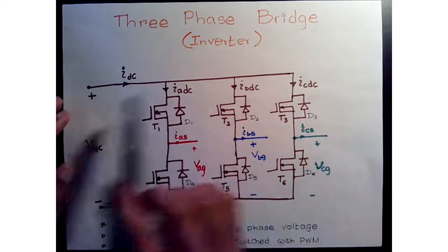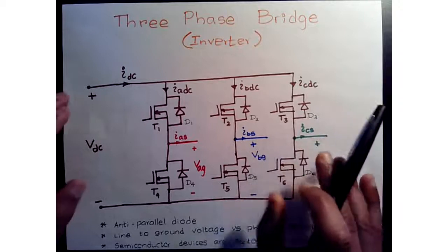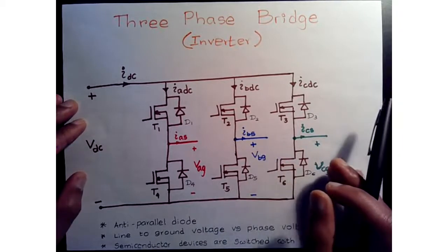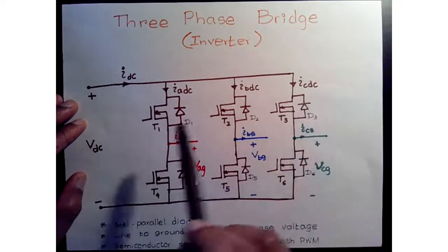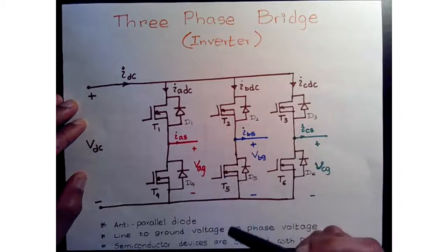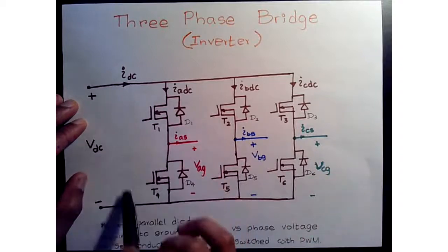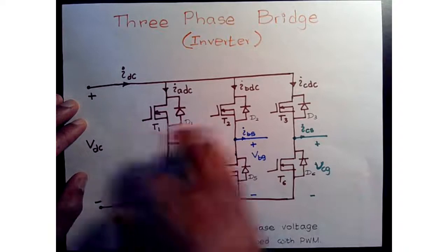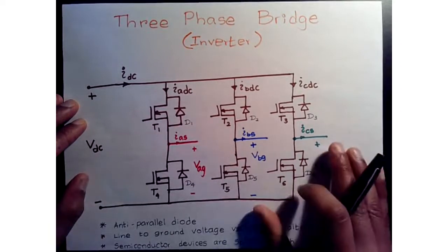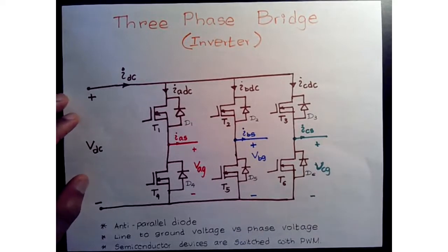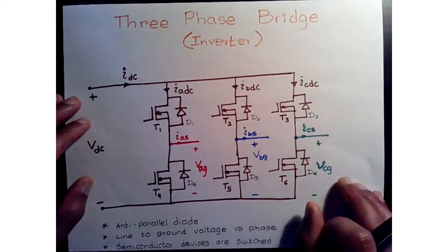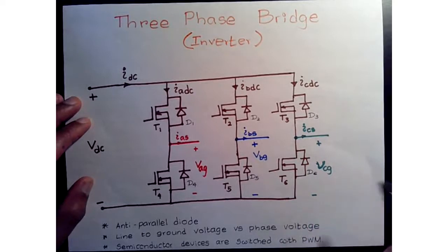Okay, so here is a standard representation of an inverter, at least from a high level. If you go down to the hardware level, you're going to see a lot more detail. You'll see the gate drivers, bypass capacitors, bulk capacitor, current measurement, and a lot of other components that go with an inverter. Here we are trying to set up the background to understand modulation strategies, so we need to understand how the different voltages are related when we apply them to a machine.